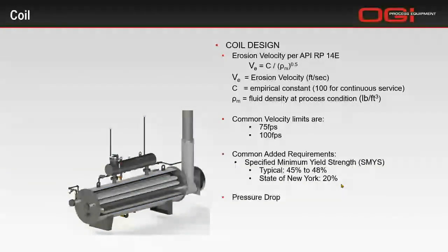And then finally, pressure drops. Our standard, or maximum standard, I would say, we won't go beyond 20 psi. Although really our typical on the quotes that Mike sizes were 10, and in many cases actually 5 psi. And common ranges we've seen are 5 to 50 psi. So if a customer tells us they're okay with 50 psi, we're just going to stop at 20 or maybe 10.